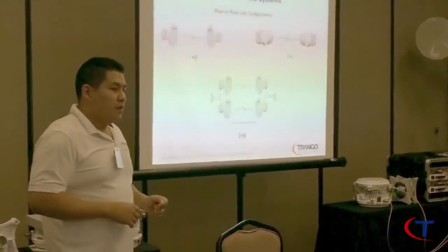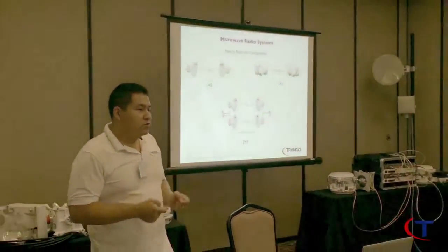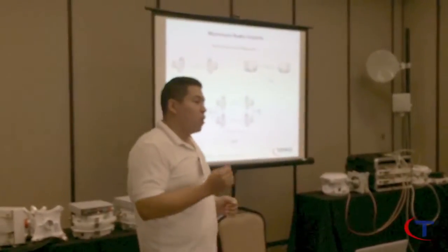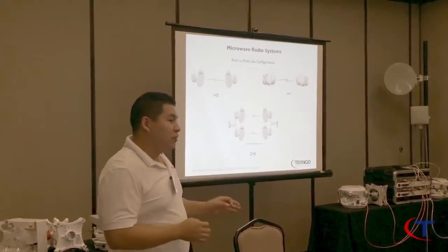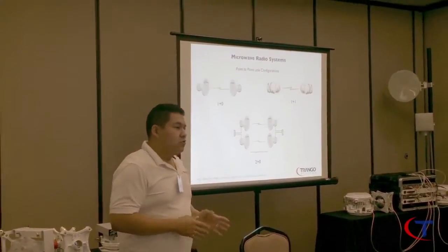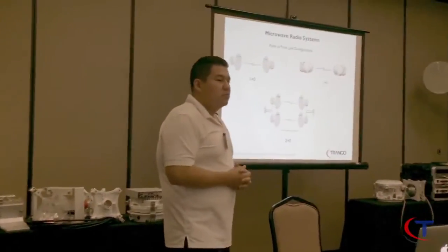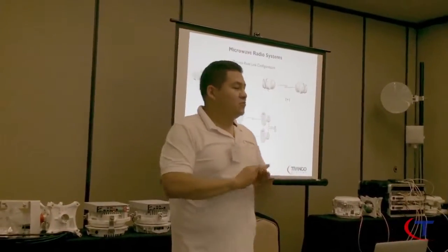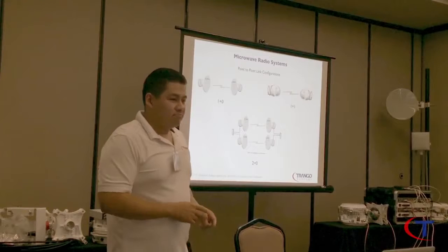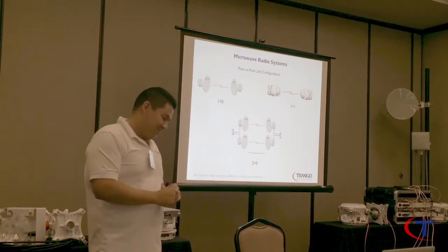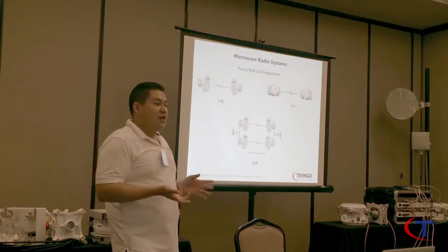1+1 system, hot standby. Two radios are active at the same time, but only one transmits. The other one is only listening to the other side as well. So the other sides are symmetrical. Same channel, same frequency. Exactly, correct. Two identical radios. It's like a hot standby radio protocol. There you go. The only thing is the other one is not transmitting.